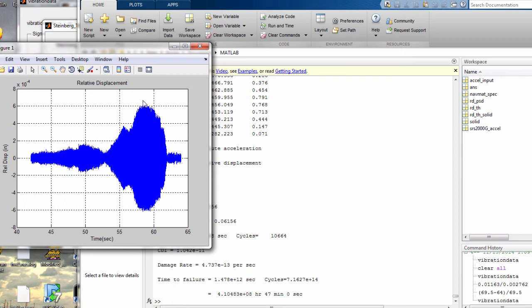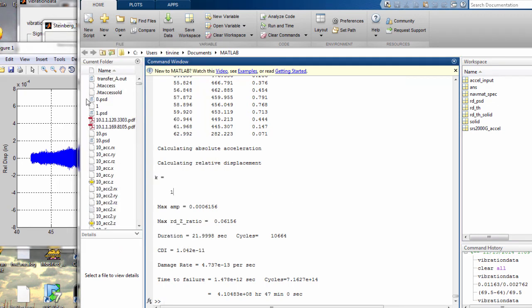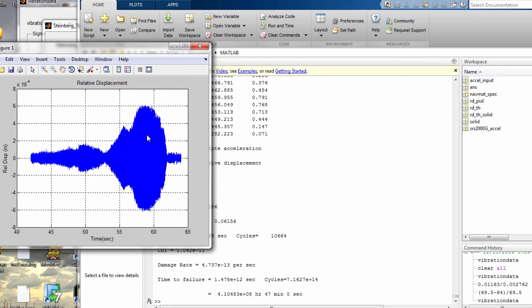And also, the higher up we go in natural frequency, the lower the relative displacement that we're going to tend to have. And that's good. It turns out for relative displacements in electronic circuit boards, the higher the natural frequency, the lower the relative displacement will tend to be. There are exceptions, but that's the tendency. So up at 400 hertz, we're in good shape to go.